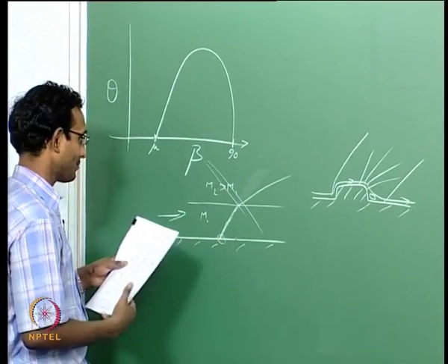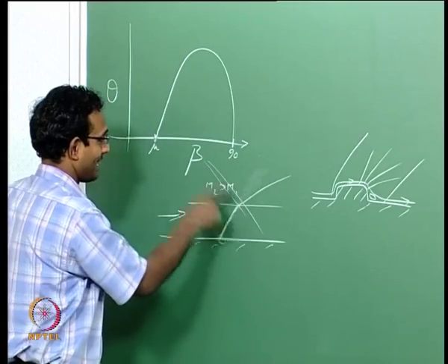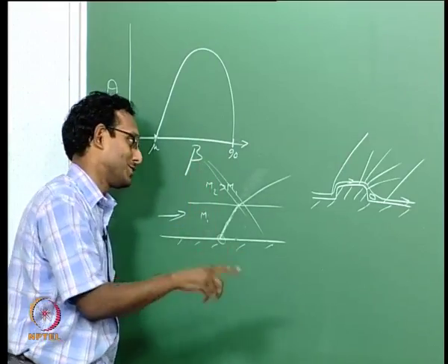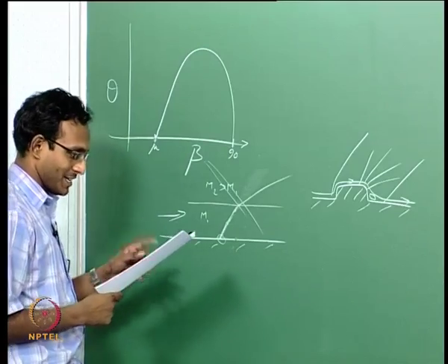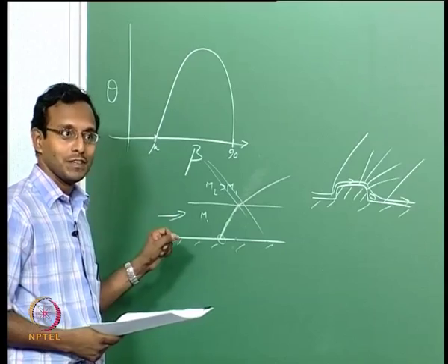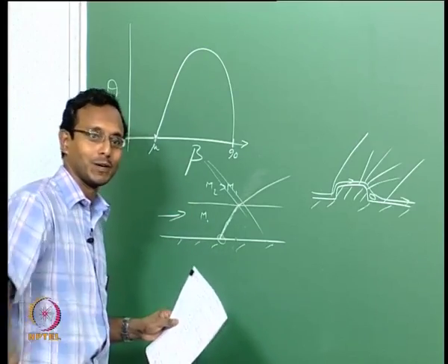That is the way you have to actually think about realizing this situation if you want to realize it. Anyways, I am not drawing exactly where the expansion fan is originating from, here or here. That I have to think through. I don't want to think through it. I just wanted to say that there is a Mach number change here. So I am going to say the next statement, which is if there is a very small change, I am going to assume it is almost a Mach wave, and that is how all experimentalists work.